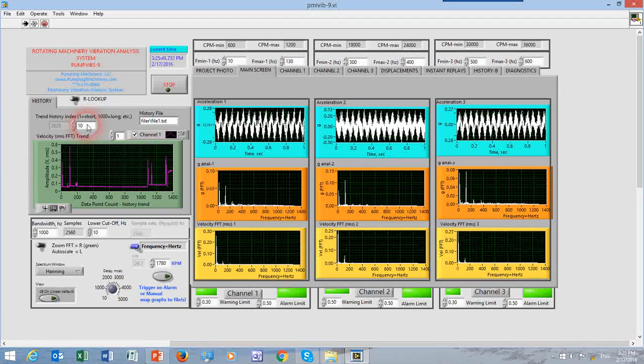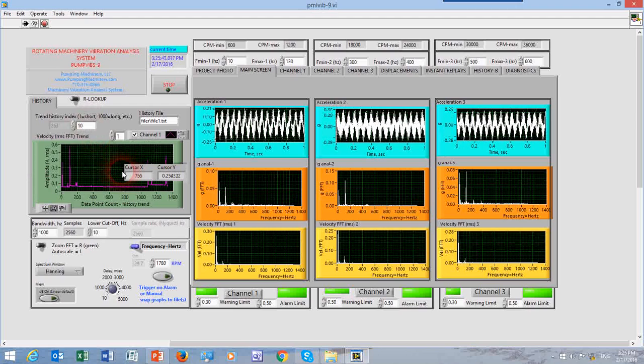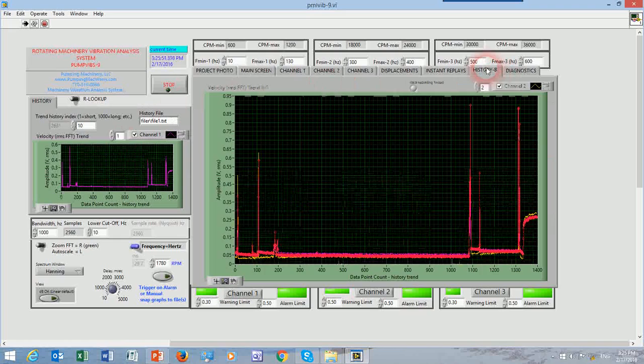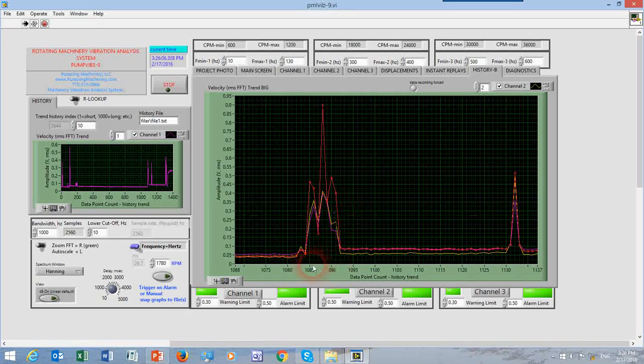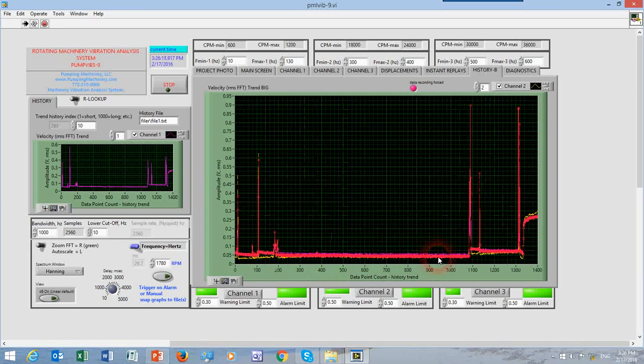That will take the data less frequently, every 10 minutes, maybe once an hour, to show you a trend over days and weeks and months. And then you can always look at this trend. You can go to the zoom feature and zoom on this portion of the screen. As I'm doing right now, you can see what happened between points 1085 and 1090. Later on, I'll show you a lookup graph, another option, where you can see which days, times, minutes, and seconds points 1085 to 1090 correspond to.